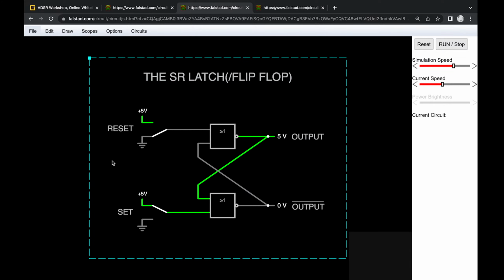With these flip-flops, we have a little bit of a limitation. This state, which we see right now, where the set is 1 and the reset is 0, is a valid state, right? This flips the flip-flop into its on state. Now, what's an invalid state is actually this: if set and reset are active at the same time. Why is that invalid?